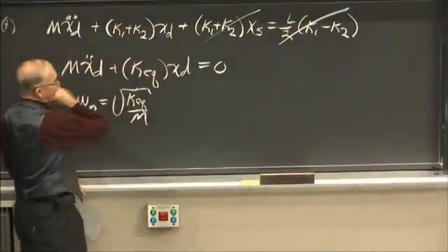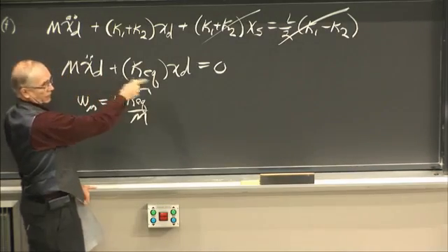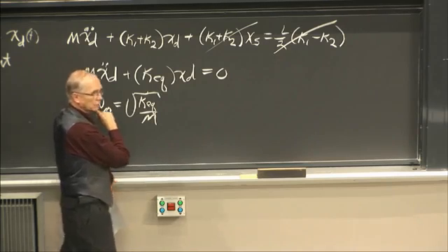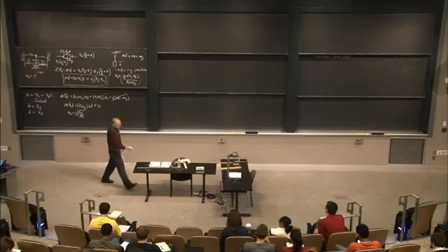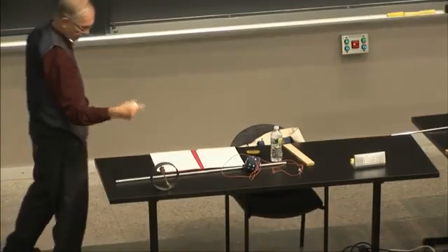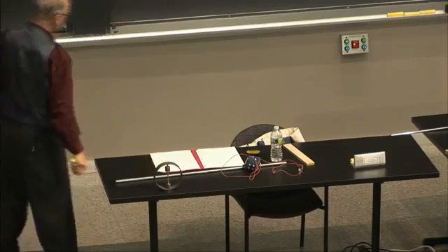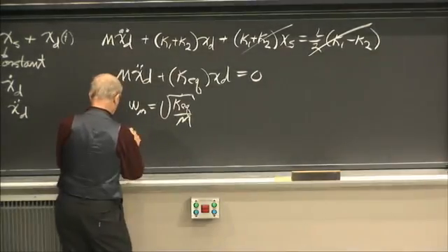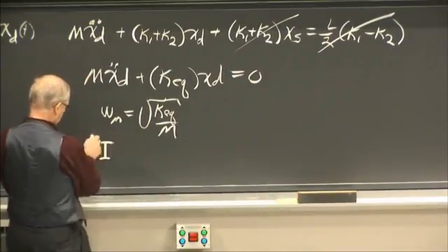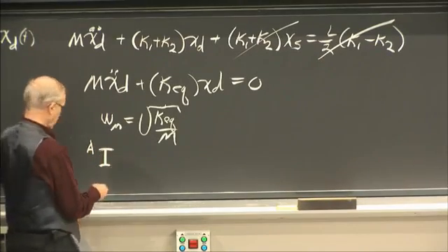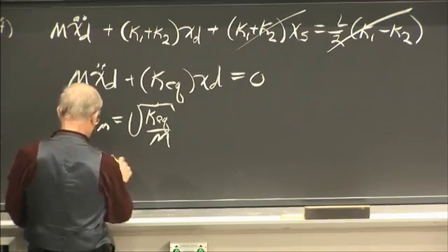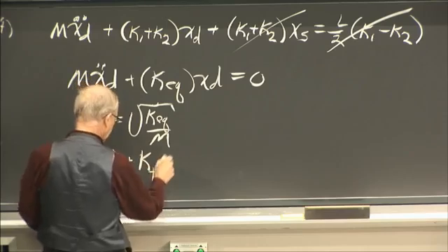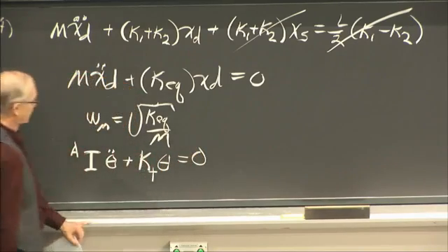Okay, first, all single degree of freedom oscillators will boil down to this equation. This one involves translation, but a simple pendulum, this object for example, is rotational, so it's a pendulum, but it's 1 degree of freedom. All pendulum problems, if you do them about equilibrium positions, boil down to some I with respect to the point that they're rocking about, theta double dot plus some k t, torsional spring constant, times theta equals 0. They take the same form.